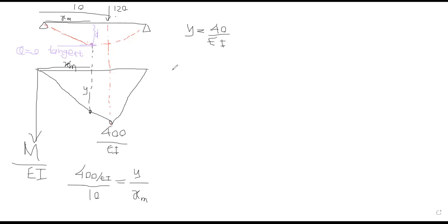Get the concept again. So if your point load is exactly at the middle, then you know the bending moment diagram is symmetric, the maximum bending moment is PL over 4, and it happens underneath the load, as well as the maximum deflection also underneath the load. But if you move the load, the system is not symmetric, right? You can't tell where the deflection would be. We need to find it, right?